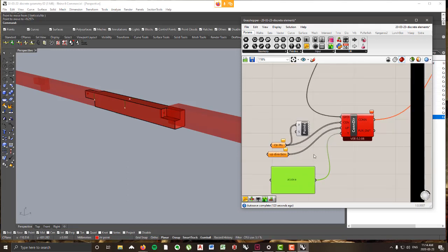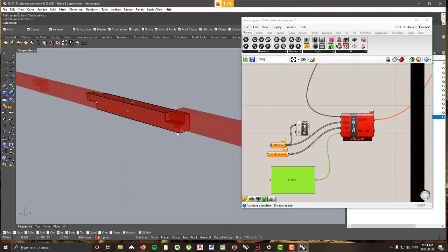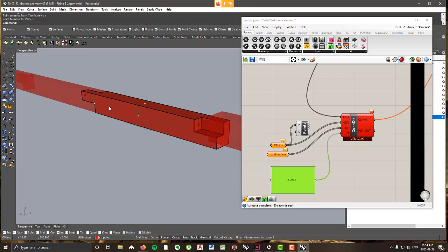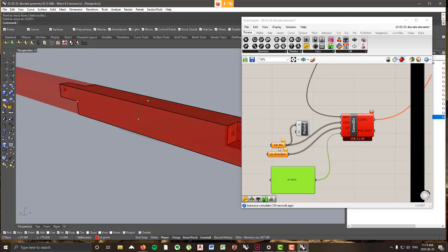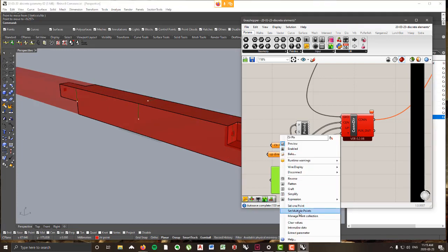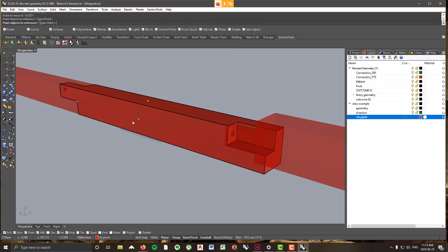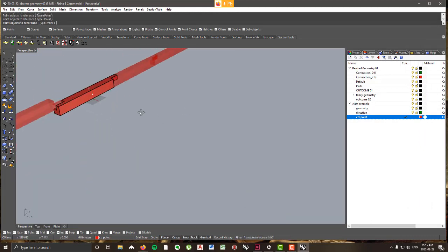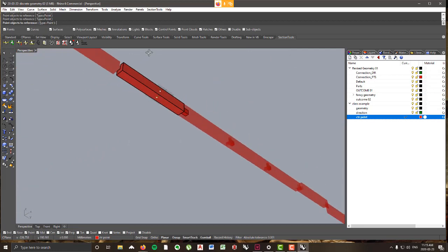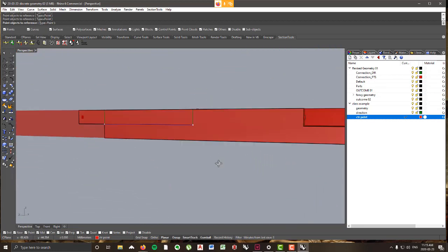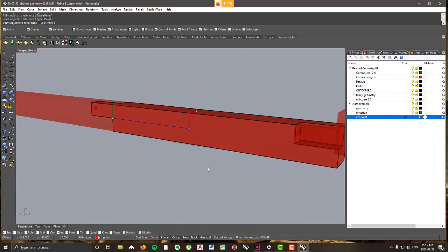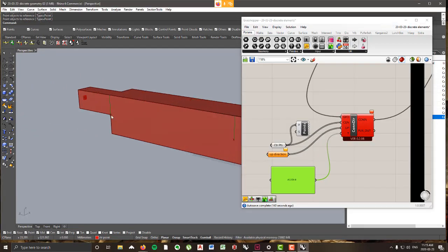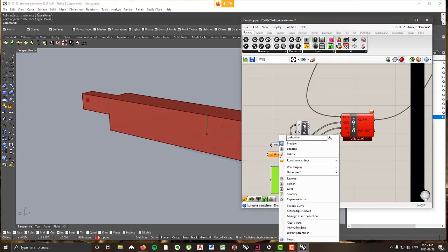We can set our center points now in, and our up directions for our sides. So why don't we do that? So we can go to right-click center points, set multiple points. 1, 2, 3. Now I'm just clicking these in whatever order because we have that little point label. We'll be able to refer to it after. I select all, I'll hit enter. And then I'll right-click the up directions and select these in the same order.